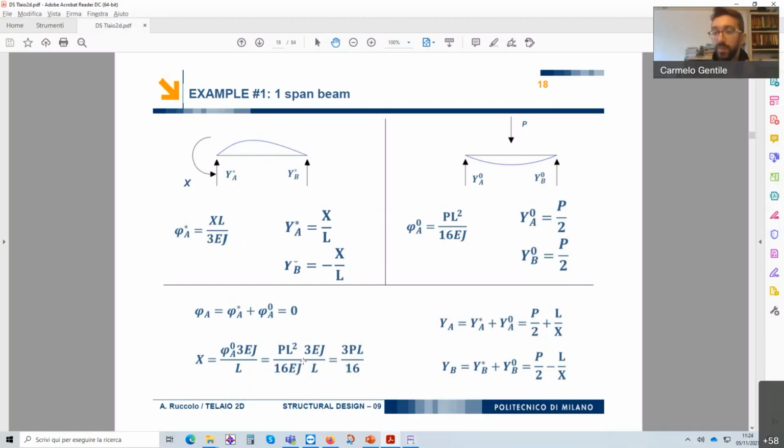If I had two beams with different materials, then I would have E1 and then E2. As we have seen last week, L is not always L. L depends on the length. So if we have a two-span beam with one span 2L long and the second one L, the flexibility coefficients will have L to the power of 2, or better, 2L to the power of 2, so we will have 4L squared, whereas the second beam will only have L.